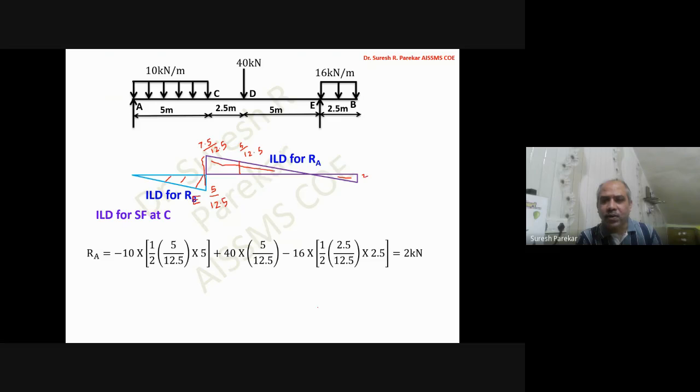And likewise, we are going to get the value of shear force, and that value is 2 kilonewton. You can calculate this value by using the reactions we have calculated. We have calculated this reaction as 52 kilonewton. Now if we take at C, then we have directly 52 minus 50, that is due to this. So we are going to consider the portion left of this, and automatically our value is 2 kilonewton.